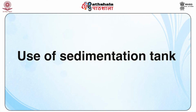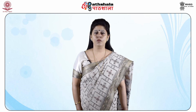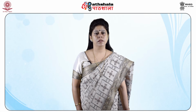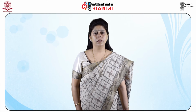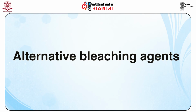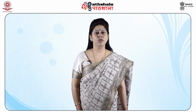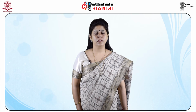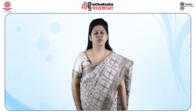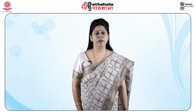The next solution is the use of a sedimentation tank. The suspended solids in paper mills are removed by sedimentation so as to reduce water pollution. The process results in particles settling down under the impact of gravity and then being removed from the base of the tanks. The next is alternative bleaching agents. As chlorine-containing bleach causes pollution, other pulp bleaching agents, that is, hydrogen peroxide, ozone, and oxygen, can be used. These agents do not leave any unwanted residues and are supposed to be environmentally friendly.